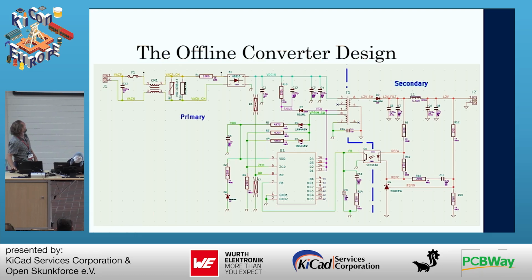Like there's a 10 ohm resistor here, that will not create a large voltage across that 10 ohm resistor, but it's residing at 220 volts. So you don't want a large clearance on those two nets, but you probably want a large clearance on every other net. So it's a good example of why we need to differentiate the clearances in the design.